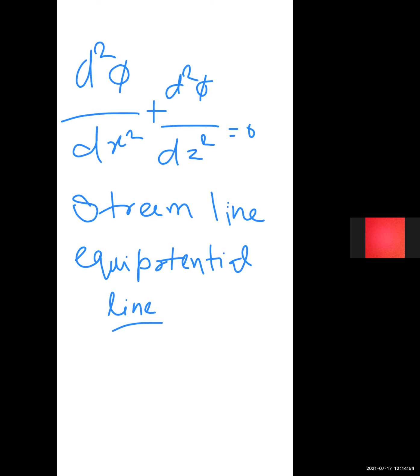Now for equipotential lines, treat the downstream bed as datum and assume no water on the downstream side. It can be easily stated that every streamline possesses a head equal to H1 while entering the soil, and when it emerges at the downstream end into the atmosphere, its head is 0. Thus the head H1 is entirely lost during the passage of water along the streamline.